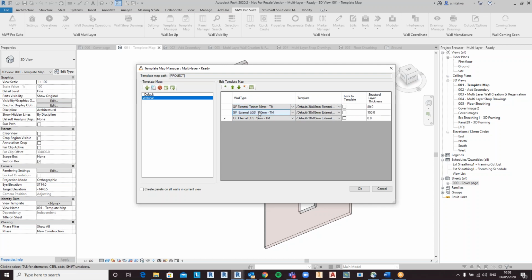And then now that I've added my wall types, I can go ahead and add the templates that I've made prior as well to this webinar. So as I stated, you can create your structural templates by simply pressing the create button, making your adjustments in the properties, and you can then save these to be viewed and exported or imported in the template manager.